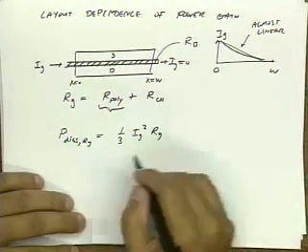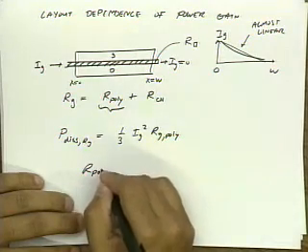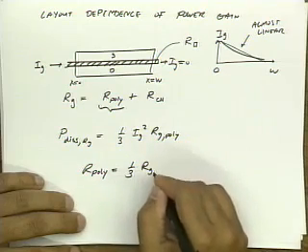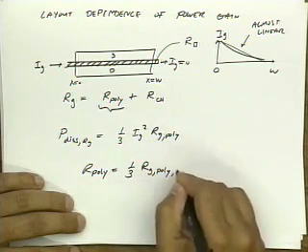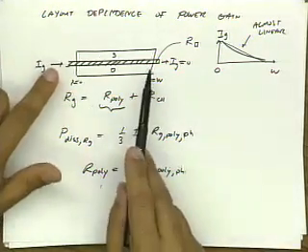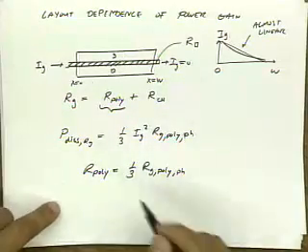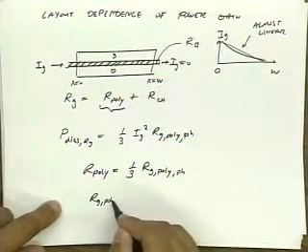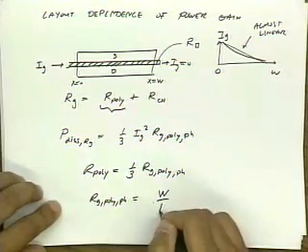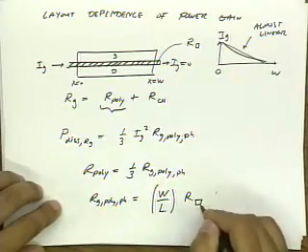In other words, R gate poly is 1/3 R gate poly physical. Again, sorry about the notation. So this is the actual physical resistance of this, assuming you put current in uniformly. In other words, R gate poly physical is W over L times the sheet resistance.